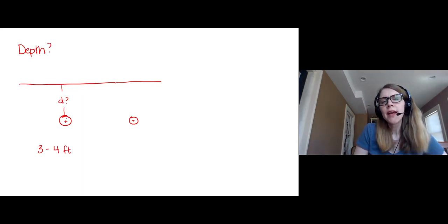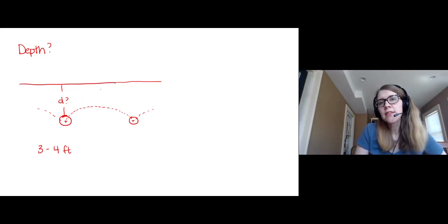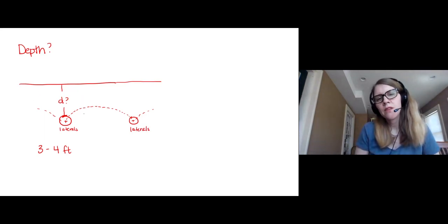But we also need to recognize that the water table between those drain lines at steady state conditions, after all of the gravity drained water has left the system, actually has this kind of humped nature where it's closer to the surface midway between two adjacent laterals. And so there's this relationship between the depth at this midway point and the spacing.